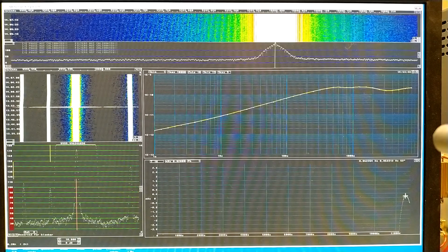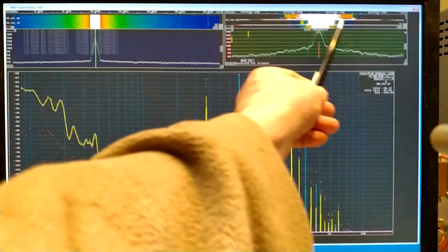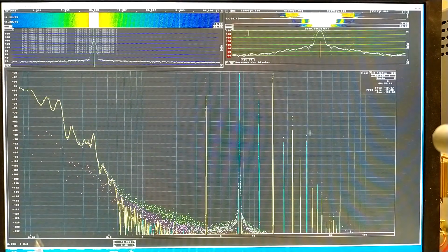And here we can easily see how it had the maximum and then turns back. Now the phase noise is much stronger close to the carrier. And you can see it here, how this has widened. And you can see here at 0.1 Hertz, I see -68. And it was about 80 before, so that is a 20 dB loss.